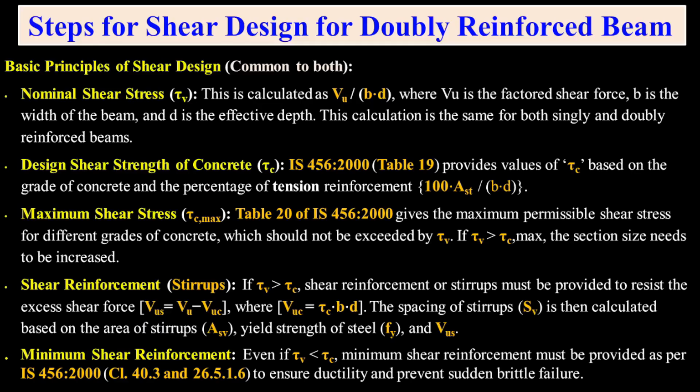Alright. Now, the question is, where is the slight variation in the results when dealing with a doubly reinforced beam? In a singly reinforced beam, we generally don't provide steel beyond the permissible limit, PT limit. However, in a doubly reinforced beam, we are often bound to provide additional tensile steel, beyond PT limit, precisely to accommodate that extra bending stress.